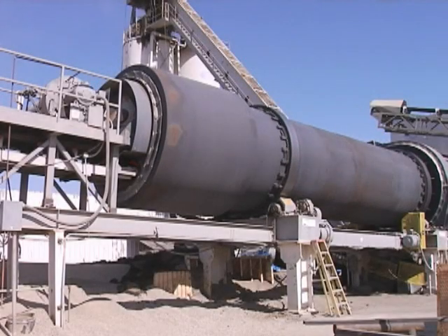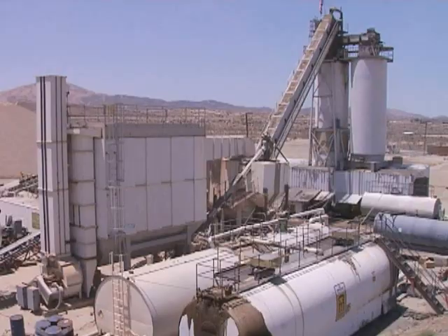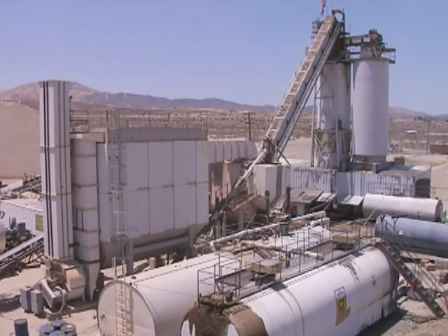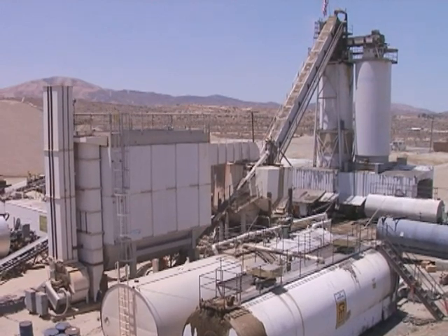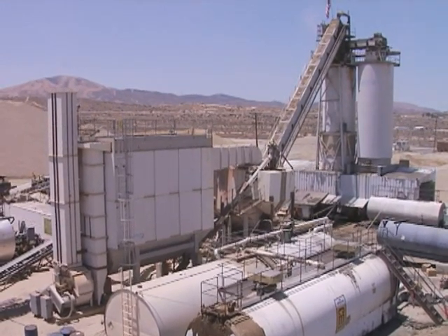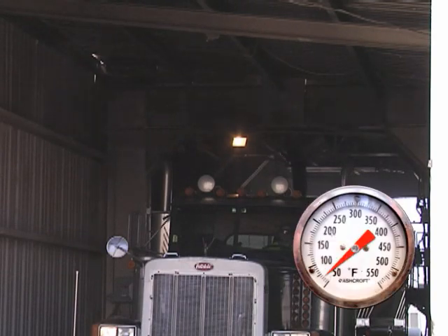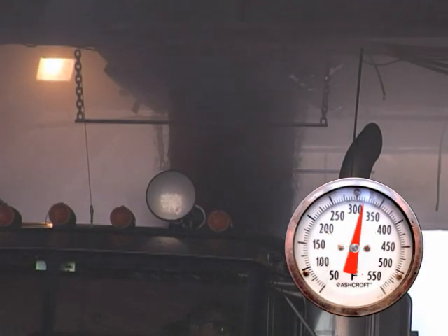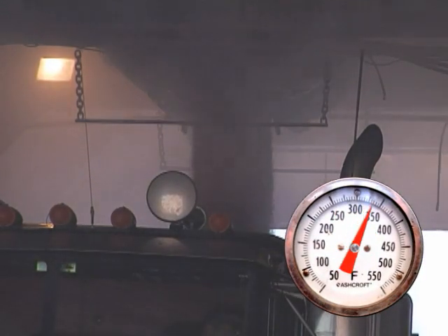The rack binder and aggregate are now combined using conventional HMA processes. The rack mix produced is now stored in silos, ready for delivery to the job site in trucks. Temperature of the material at this point should range from 320 to 335 degrees Fahrenheit.